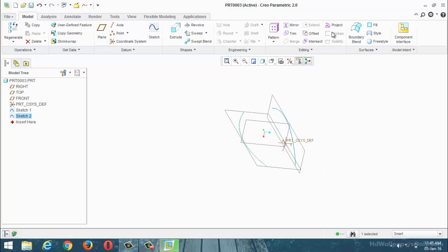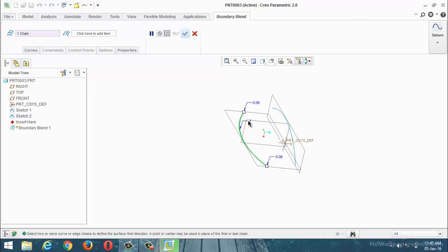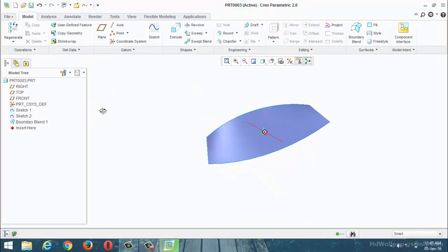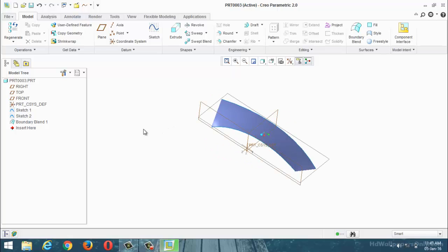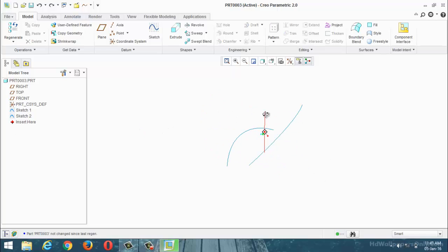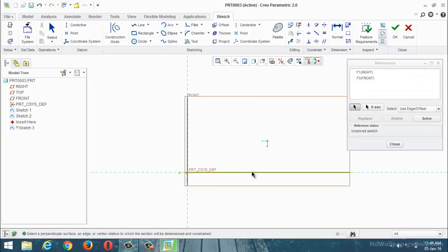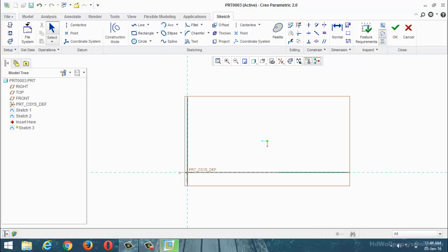Now for that purpose, now see here, now select the boundary line. First one is already selected, again press the control, select this one, just okay. You can create a surface between two curves. Again you can specify the guide curves also. Now again I am going to select this one, sketch, set it to sketch view. Now I am going to specify the, just activate this reference curves, again this reference. Okay, then you can see here, now I am going to define the curve directions.